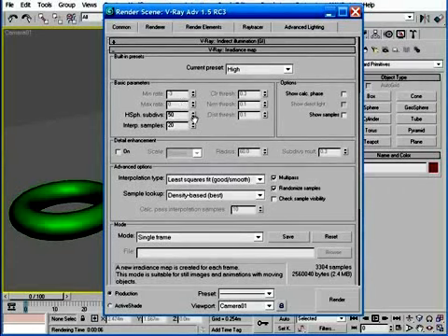By default, the hemispheric subdivision value is set to 50. However, I would really recommend avoiding such a high value because it can create some excessive render times. You always want to experiment with any scene, but a good number to start with would be 20. And if this value gives you what you want and doesn't create any problems in the GI you're seeing, then don't increase this value.